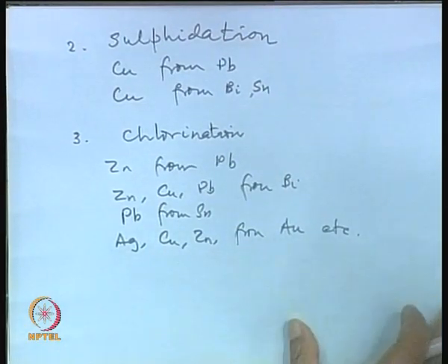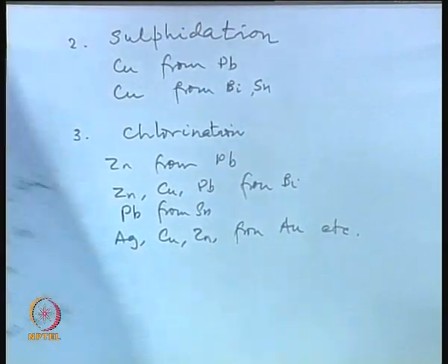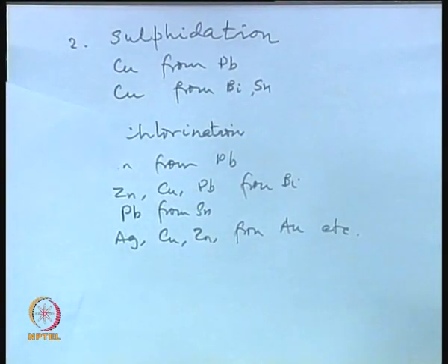So, the basic principle in this sort of fire refining is very simple, that we are keeping the crude metal in the molten state under oxidizing conditions. We control the partial pressure of oxygen at various levels. We can remove the impurity elements either as volatile oxides or as solids, which will come out as a slag, which will be skimmed off periodically. Very standard technique.